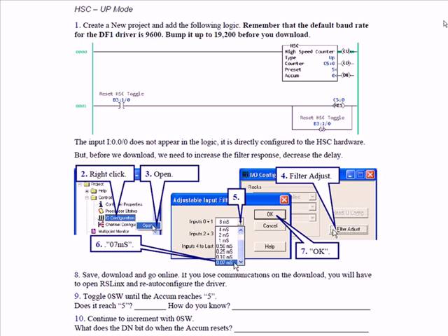So we have a little piece of code, rung 1, and it says reset high speed counter toggle. We're using an internal bit, B31:0, and we're using the toggle function in RSLogix 500. So if you right click on B31/0 and select toggle, it will change the existing state of that bit.